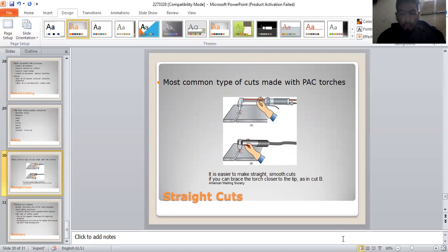There are two types of cutting. The first is straight cutting. The second is irregular cutting. By using shading, yes, we can convert the irregular surface to a fine surface, but it is not as fine as what we get from laser, because in a plasma torch machine we continuously supply heat, so it is not possible to have a very clean and clear surface in plasma cutting due to the continuous supply of heat.